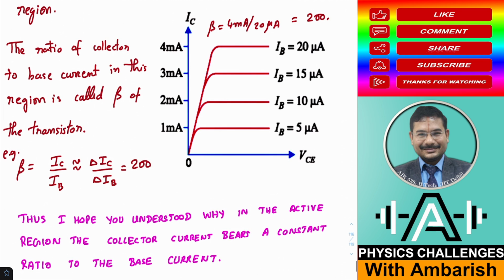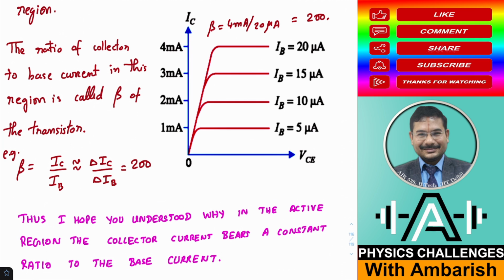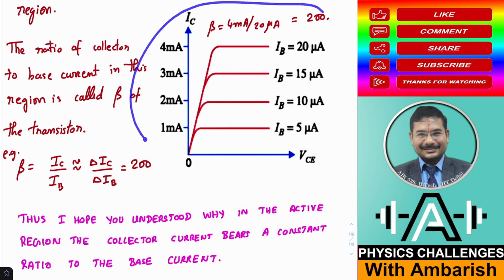So you can see in the active region, because the ratio of base current and collector current is constant, that's why we were taking collector current as simply beta times base current. I hope you understood why in the active region the collector current bears a constant ratio to the base current. Okay, so this is it. I deliberately chose this figure so that this concept is very clear.